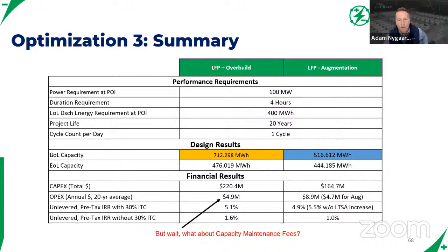Yeah. And if I can answer one more before we dive into your augmentation strategies, Sherif, there's the question on whether you're considering a DC or AC augmentation strategy. We've really only talked about DC here. Part of the reason is that if you go AC, that means you're adding more inverters. If you're adding more inverters, you're changing the dynamics of what you agreed to in your interconnection agreement.